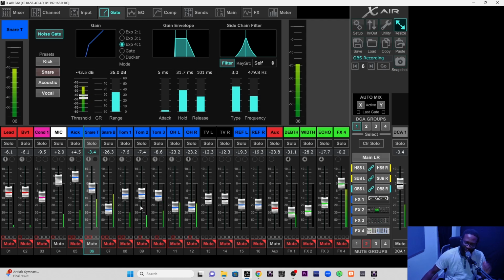So somewhere around there. Now you can see that the gate has turned off a lot of the noise that is there. All those unwanted signals, the gate has turned them off, or turned them down anyway. That's the main job of the gate. So let me do an A/B as well. Before, you see a lot of these cymbals, a lot of toms, but now put it on. We're hearing only the signal.